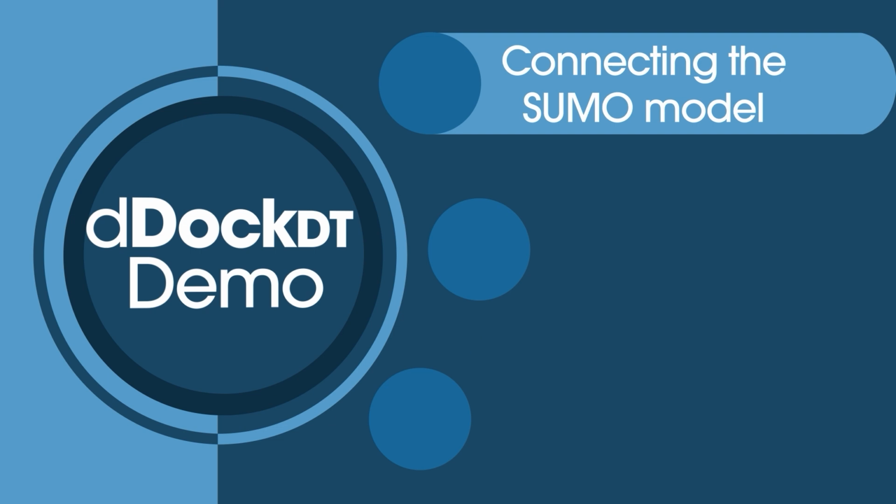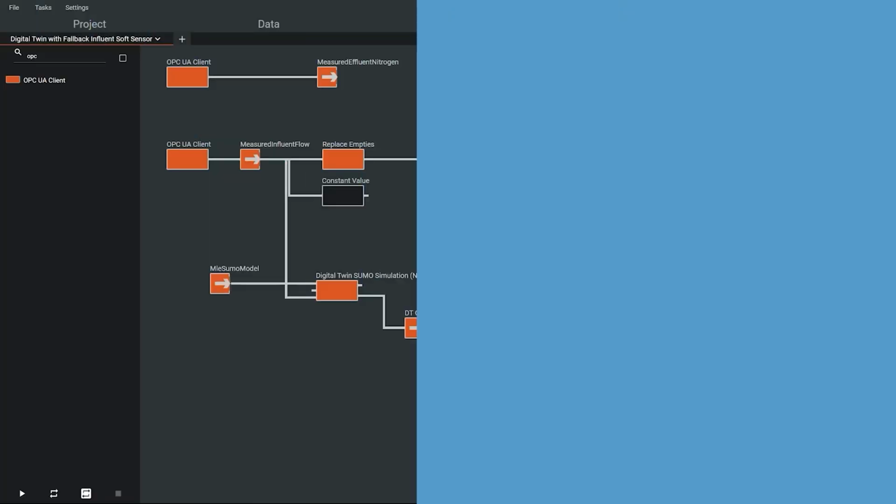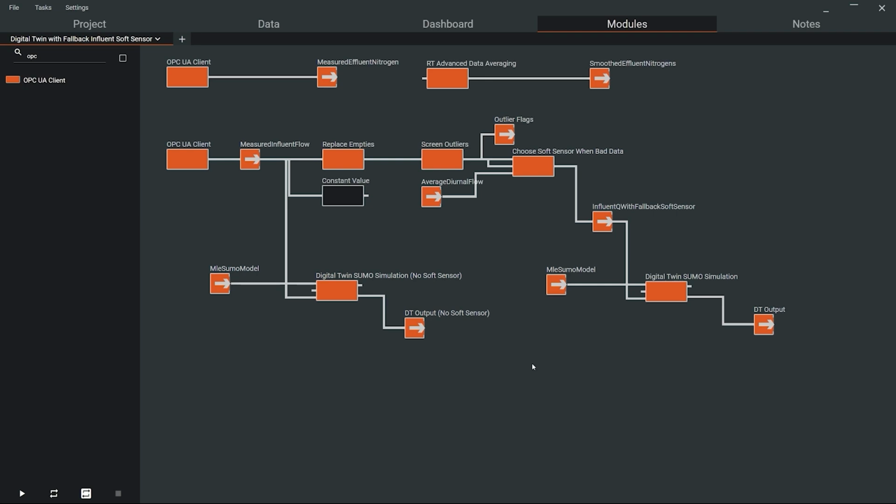One feature of dDockDT is its ability to ensure data quality and substitute alternative values when an error is detected. In the previous digital twin, the influent flow as measured from the plant was fed directly to the model without any error checking or data analysis. Here we show a more complicated digital twin setup, where we are illustrating the need for real-time data quality assessment prior to sending the data to the process model.